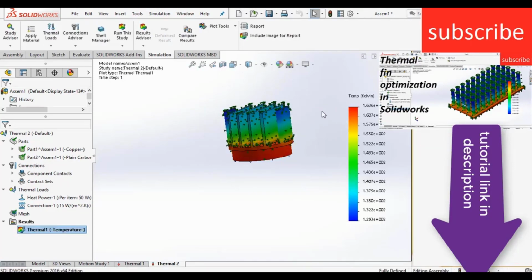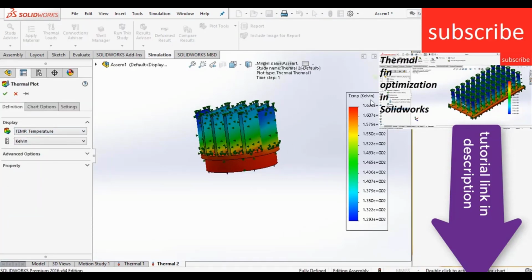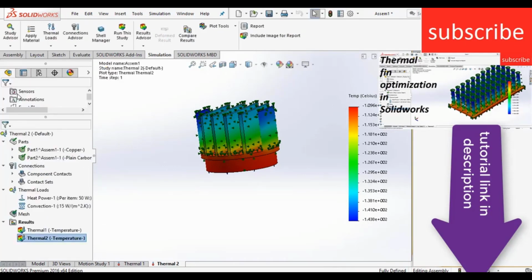As you can see, my result just came out. So click on result, click on define thermal plots, because currently the temperature is in Kelvin and I am not comfortable with Kelvin. I am comfortable with Celsius. So click on Celsius, and here you can see that the temperature is negative. A question arises, how is it possible that a temperature comes out negative?